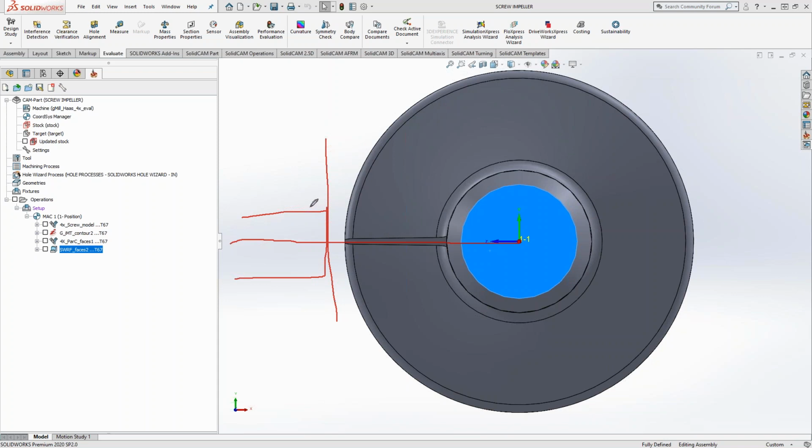The walls of the pocket would have to allow for the tool to be parallel to it. Or else, if we draw something over here, so there's my tool, any wall that's not parallel to the tool vector like that, we're going to get some excess material left behind here, because that tool can only be in that one angle.